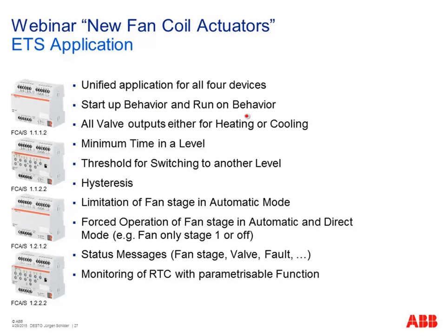Start-up behavior and run-on behavior. Start-up behavior means if you switch on your room temperature control, you can decide in the parameters whether it shall start maybe with level 3 for the fan, maximum cooling or ventilation for 5 minutes. This is adjustable. We had it already before. New is the run-on behavior. I explain it later in a separate picture, and that's a new and nice feature. Very often required by our customers and now also available in the software.